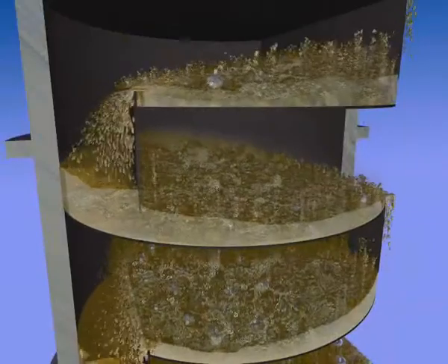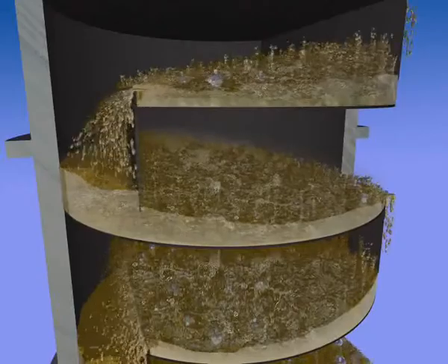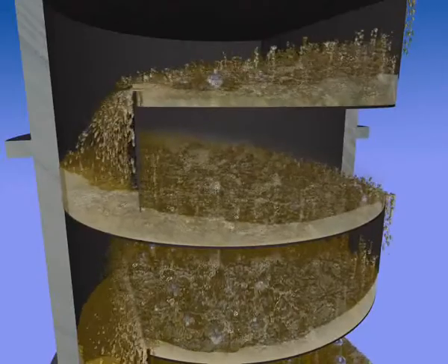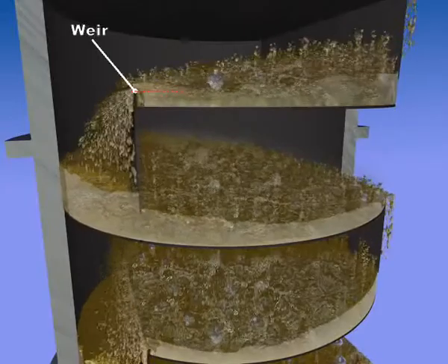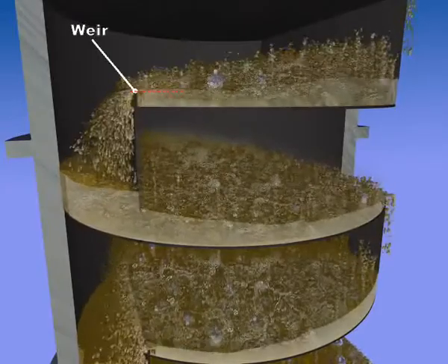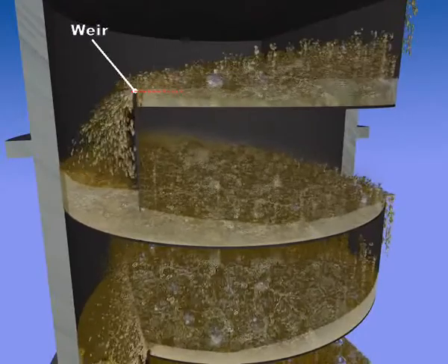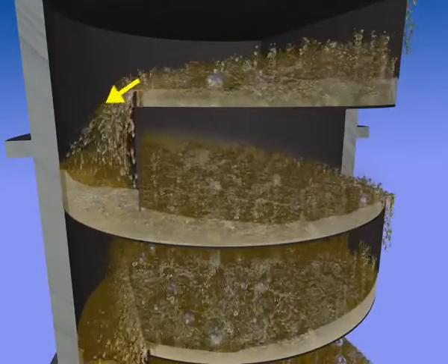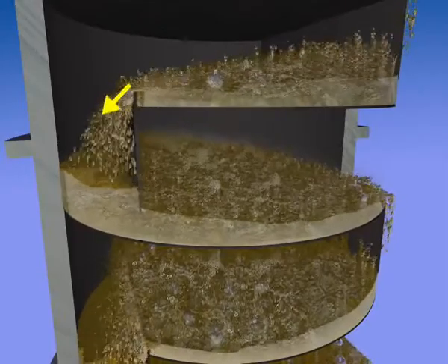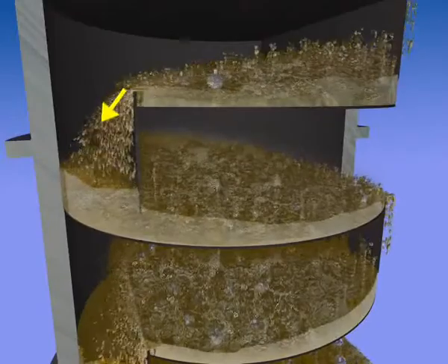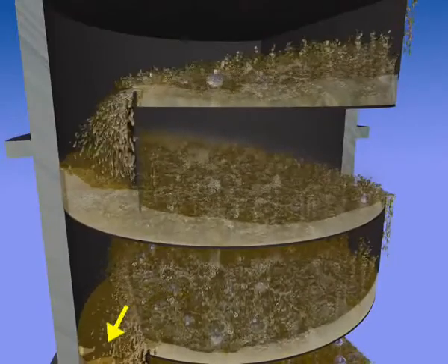The liquid on the trays completely submerges the bubble caps on the trays. As the liquid is heated to the point of partial vaporization, the surface is quite dynamic. The weir on the tray is designed to maintain the appropriate liquid level and therefore the hold-up time on the tray. Additional liquid will flow over the weir and accumulate between the downcomer, the shell, and the tray below. Here the process will repeat itself, thus creating a downflow of the liquid.